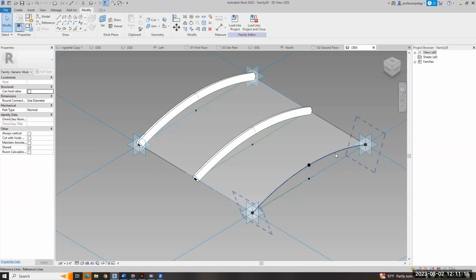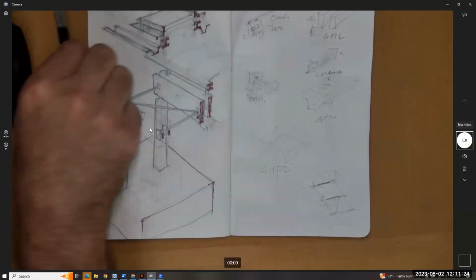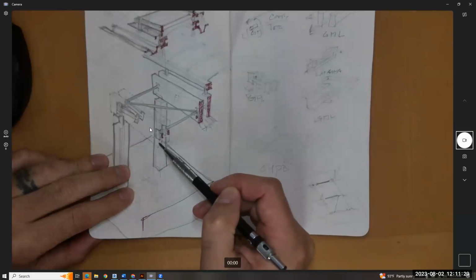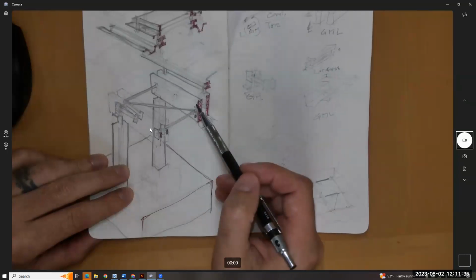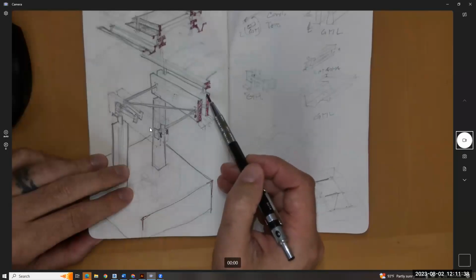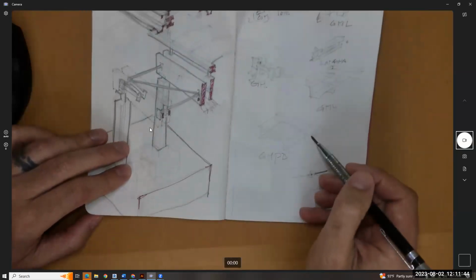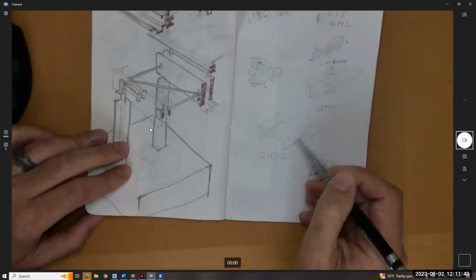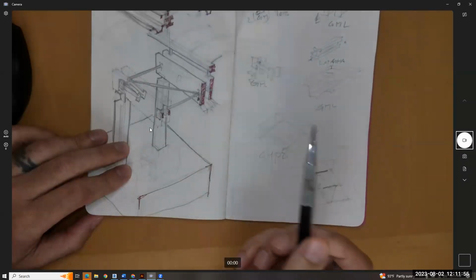This arc is going from this point to this point, right? In the grid, let's just look at our drawings. Does the arc go from the center line to the center line, or does it go from the center line of the wood to the center line of the wood? The arc is inset per bay. It's not there. So I realized, oh, I was supposed to actually create it to where there's a beam and a beam inset so that they're centered over that. That way I can snap to the same grid that this is on, right?